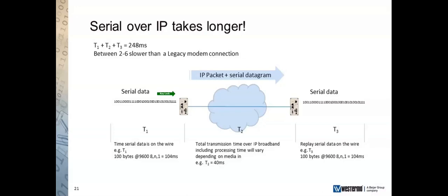So we can see here that if you've got a network or a system which is time sensitive, maybe using Modbus, or some other polling protocol, and maybe you've only got a 200 or 300 millisecond window to send and receive the data, then we could start getting close to the edge of what would be classed as a failure in the message type. So it's not a disaster. There are ways around this.